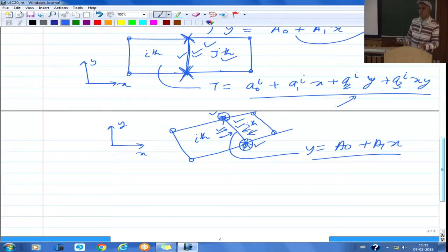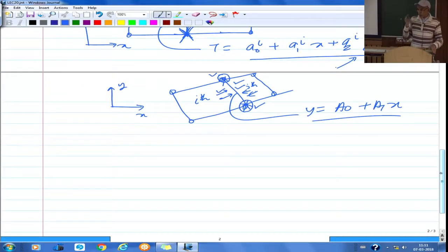So, regarding convergence, when you solve a certain problem, you need to discretize into a number of elements to make sure that if you further increase the number of elements, the results do not change. So, that minimum number required to get the accurate solution would be less for a large size problem in case of 9 noded element compared to 8 noded element, because it has an additional term. So, it approximates the temperature more accurately within the element. Okay. So, are there any other questions?